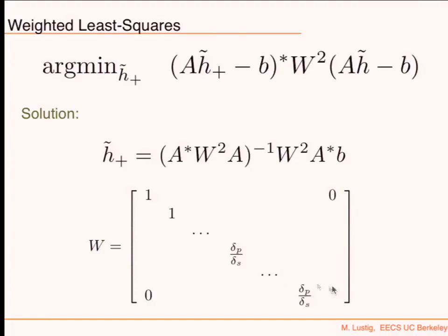Okay? So if we're going to put more importance on the passband with respect to the stopband, then this will be positive. The opposite. Sorry. Yeah, no, this will be positive. And then if we want to impose more, well, I guess you can think of delta P to be how much ripple you're willing to have in the passband.